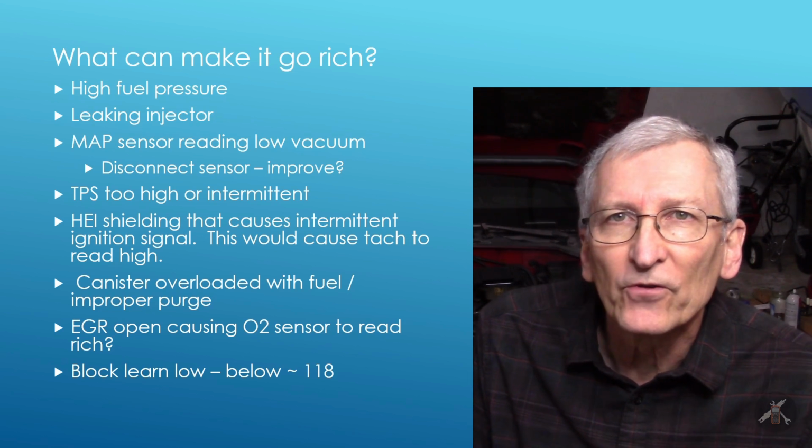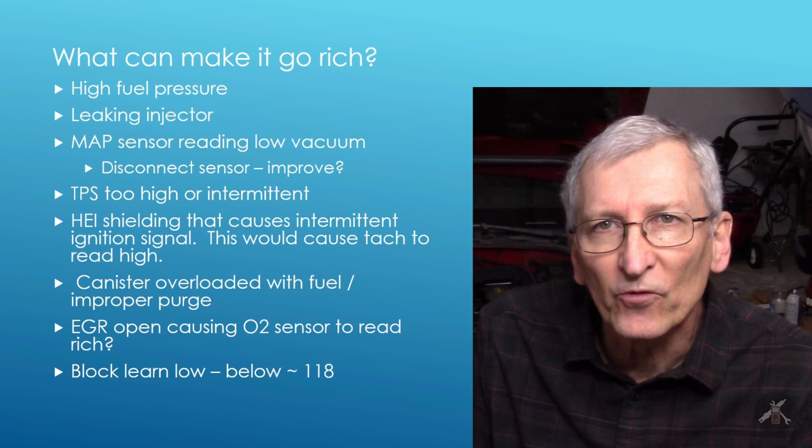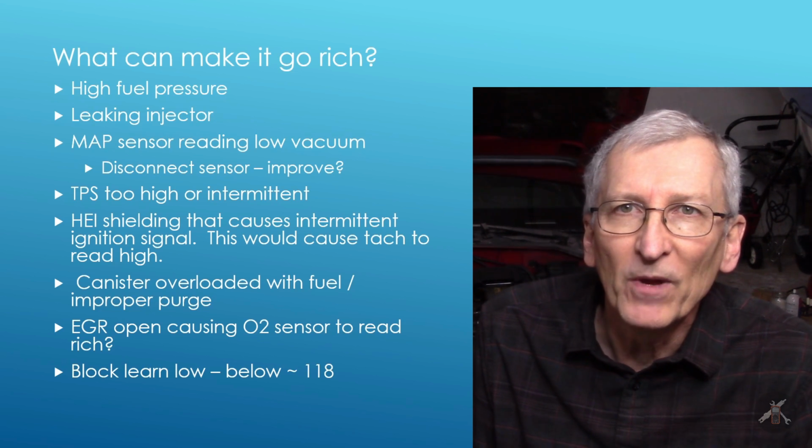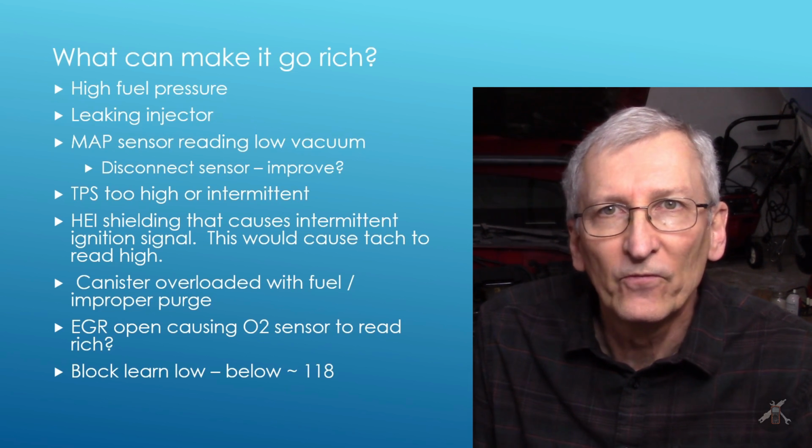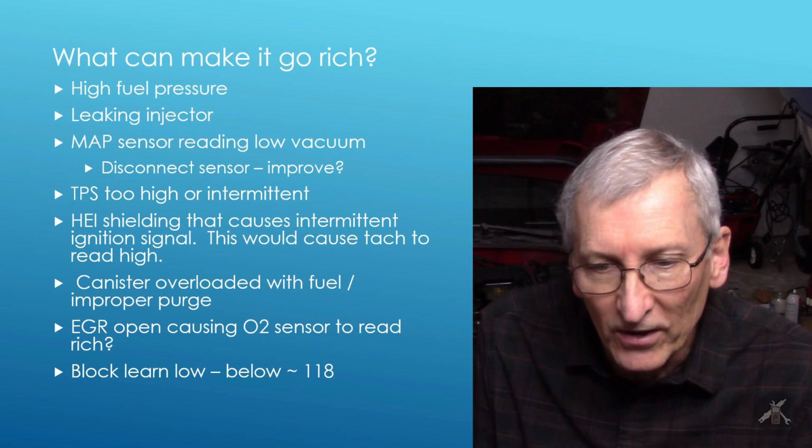Is your charcoal canister overloaded with fuel because the purge system's wrong? And in some cases, you may have to look at the canister itself. Does it smell bad? Is it full of fuel vapors or even fuel liquid in some cases?